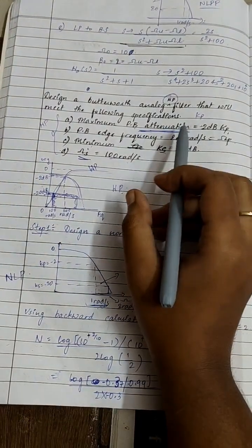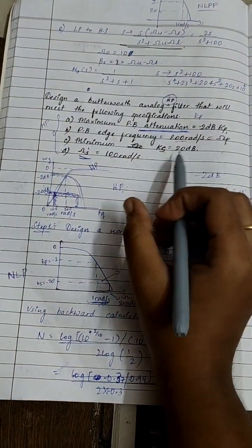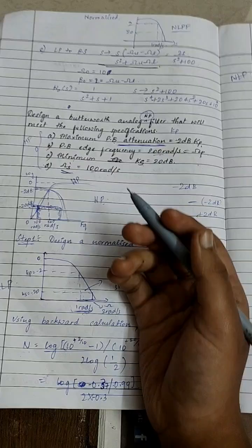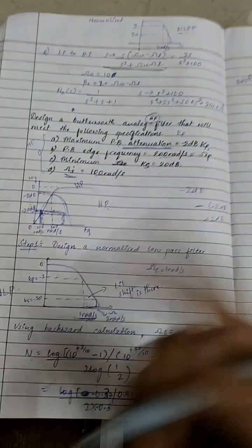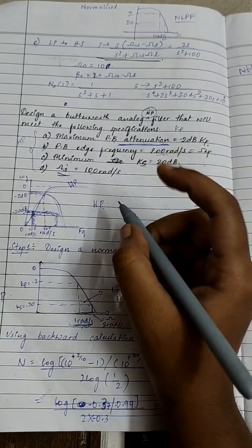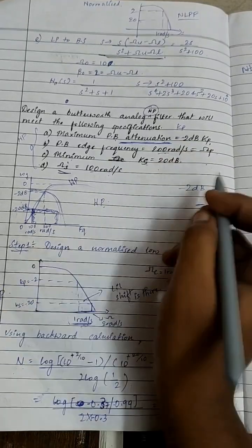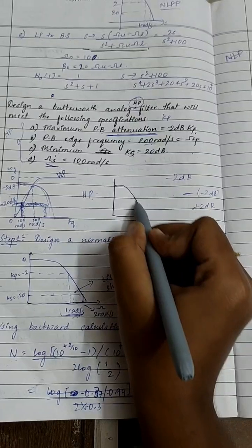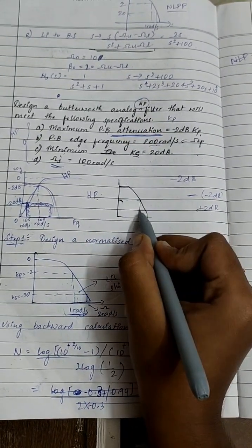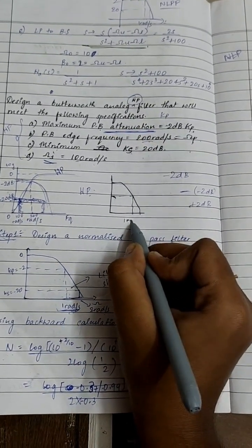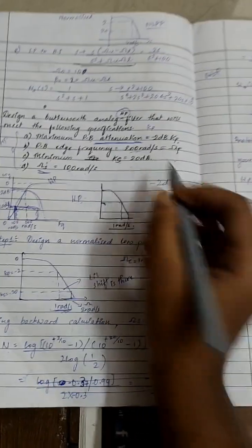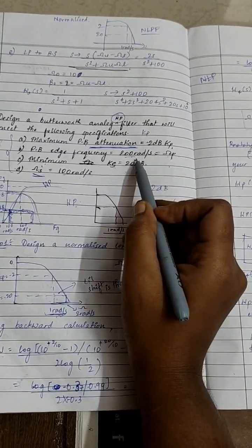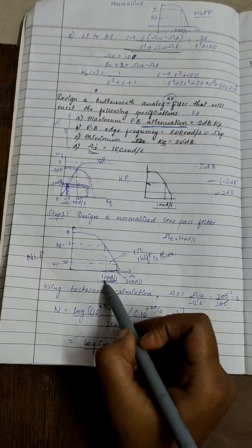Okay, so here they've given us maximum cutoff, that is kp is given, omega p, ks and omega s. Here what you have to basically do is, first here there's a trick. I said you have to use normalized low pass filter for any filter designing. So when we use normalized low pass filter, our omega p will always be equal to 1 radian per second. So here we have been given that is 200 radian per second, which should be converted into 1 radian per second.